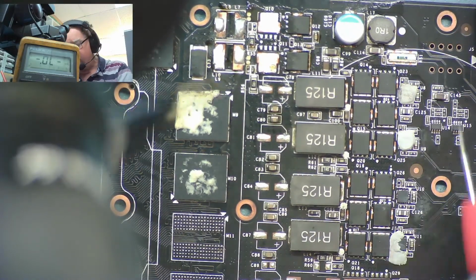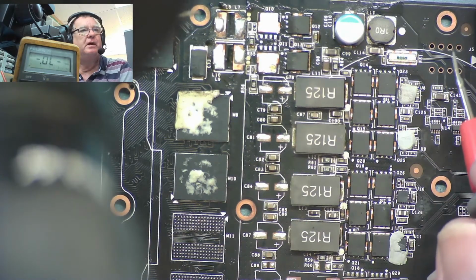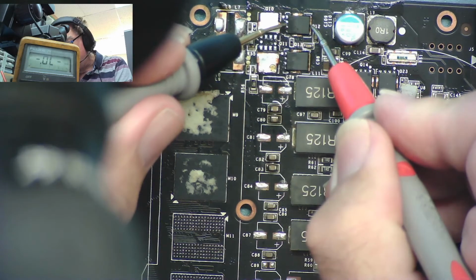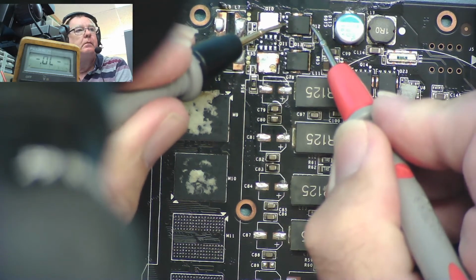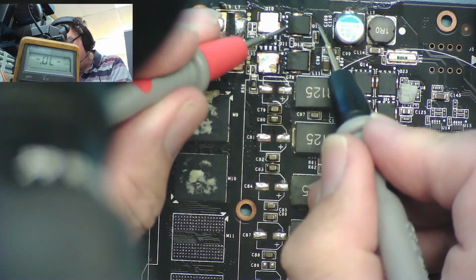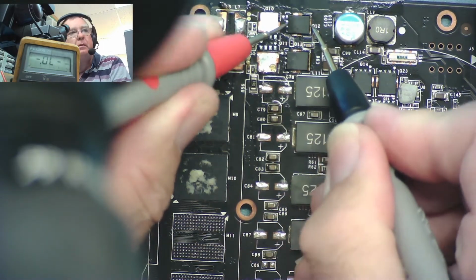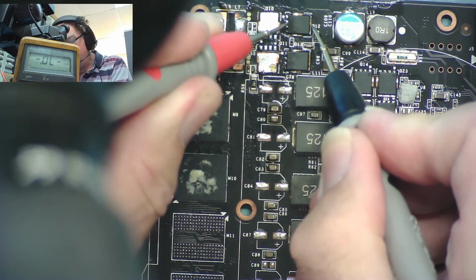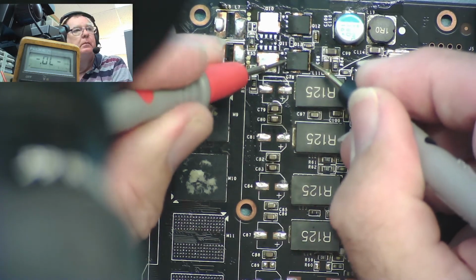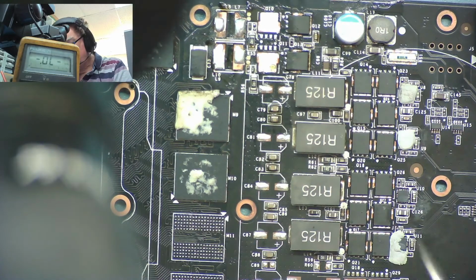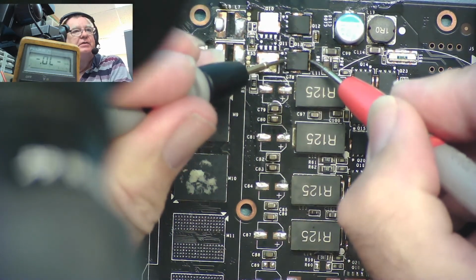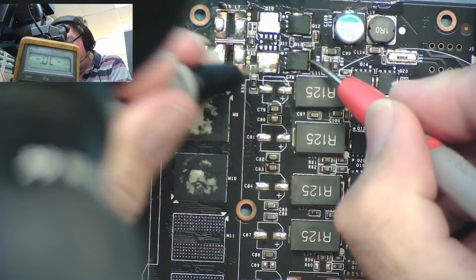So let's see if it actually works in circuit. I've never tried this before, by the way. It's the first for me. So let's have a look. So across the MOSFET, zero. Another way I'm expecting to see the diode junction, I guess. No, I see zero either way. Let's try the other one. Okay, that doesn't seem to have the diode in, but fair enough, it's reading open circuit.